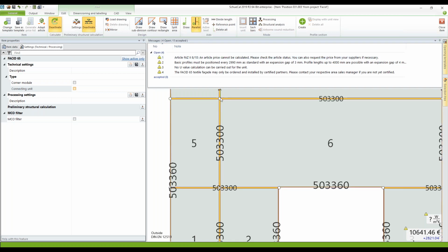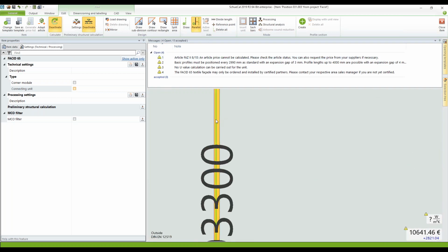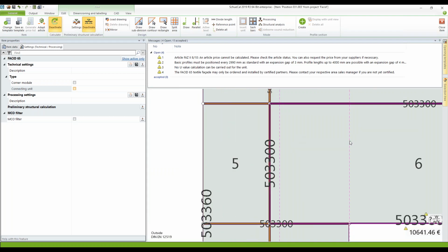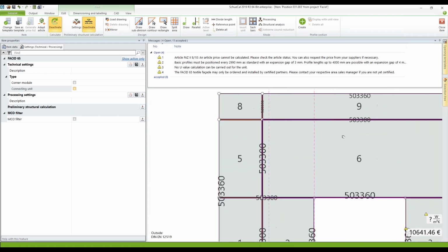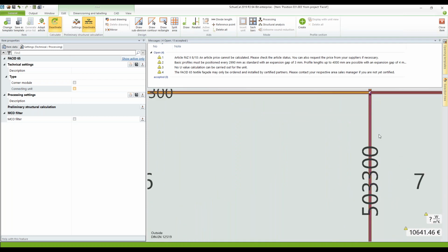If you click on parallel, and we'll zoom a little bit more into the detail, you take the center line, and I want to add 150 millimeter to the right. And I use this function again, exactly the center. The distance should be 1200 to get the next line here, as you can see it here.